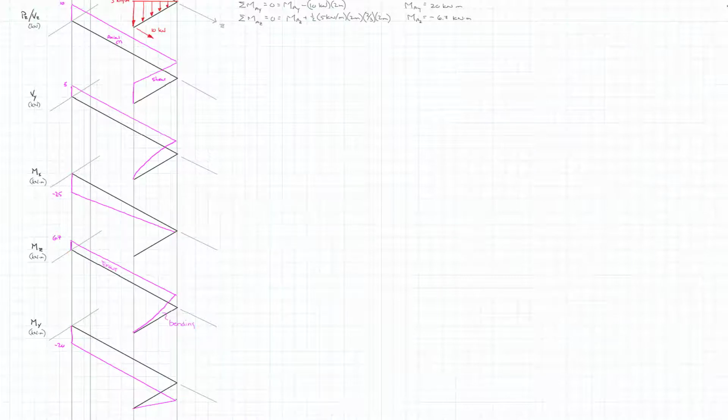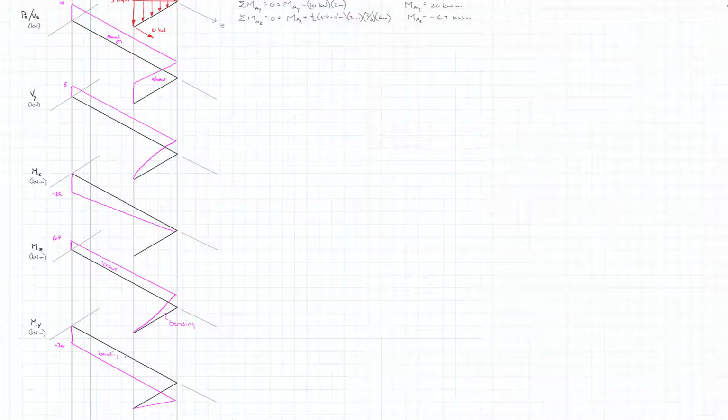And so where this is bending in here, and we look, so this is bending about the y-axis, which is the vertical axis. And so if we're bending about the vertical axis between B and C, it is also bending out here. And the moment x would have been torsion between B and C, but it's got a value of 0, so we're not really worried about it. And so that's our graph.